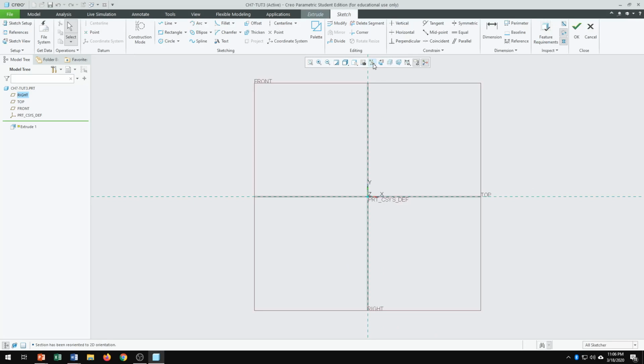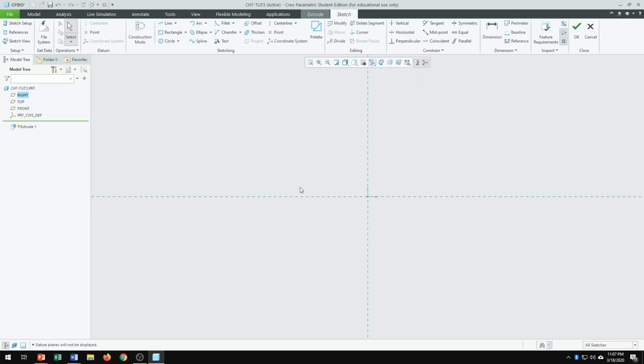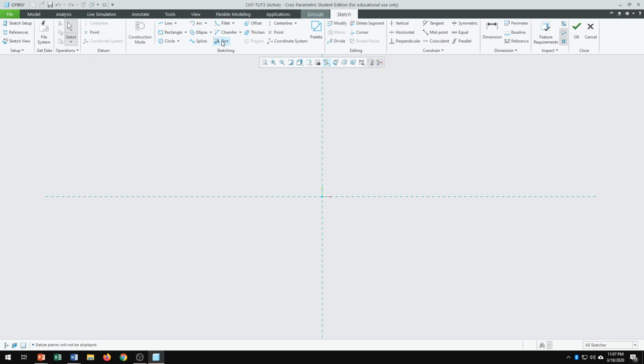Okay, by now these are the steps that we have done many times, so it's straightforward, and there is no need to show center line or put a center line on the y-axis and x-axis. All right, so what you have to do is create a rectangle on the first quadrant. Okay, start from the origin. That's the origin. You stretch the rectangle, you give the dimension of 5.5 in here, and then we're going to give a dimension of 140 for the width.